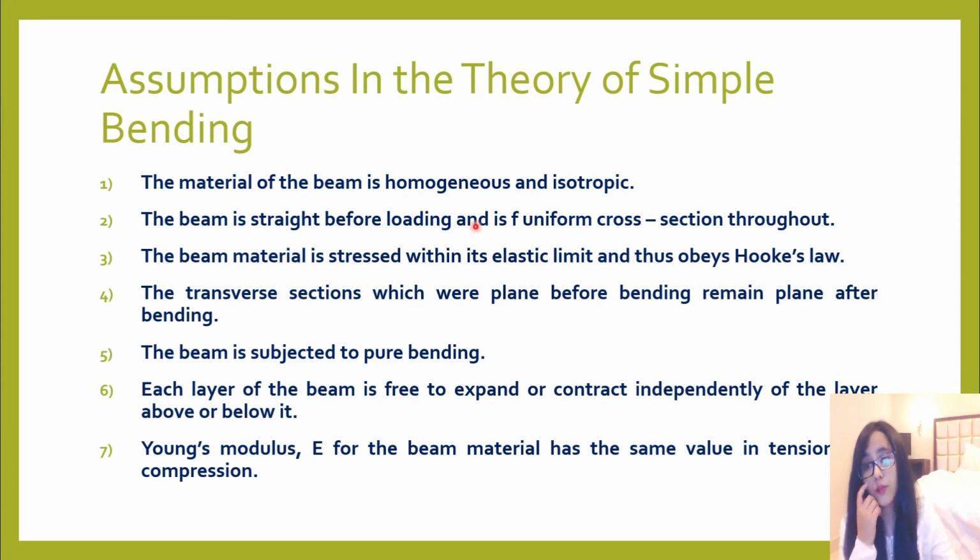Okay. Fourth point says the transverse sections which were plane before bending remain plane after bending. तो जो transverse sections हैं, those transverse sections which were plane before bending will remain plane after bending also. Okay. Fifth one says the beam is subjected to pure bending. आपको pure bending का concept पता है.